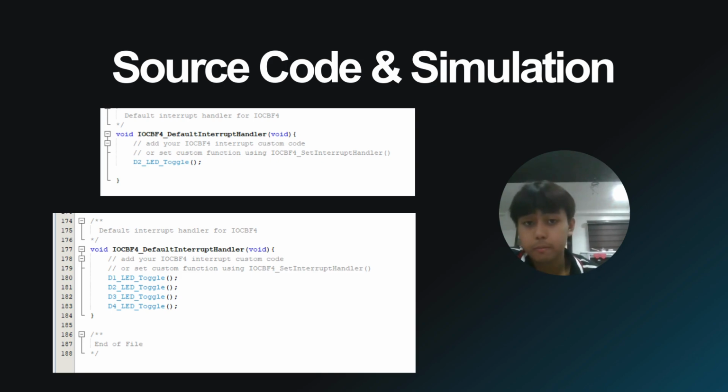on or off. For the multiple LED setup, the interrupt on change configuration of the switch was configured to activate on a negative edge. Four LEDs were connected to pins 3, 4, 5, 6 respectively, and they are connected in a configuration like in part one, the one LED circuit.